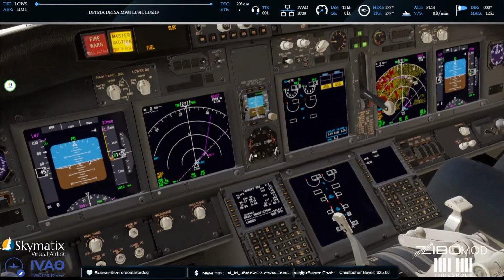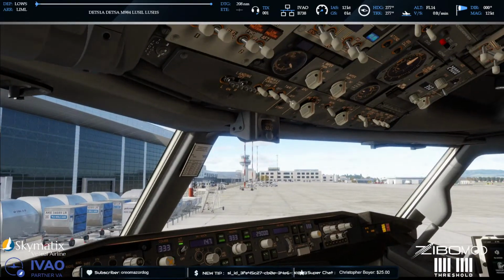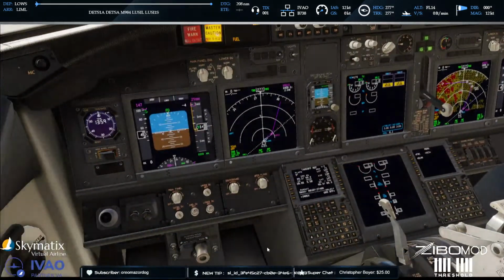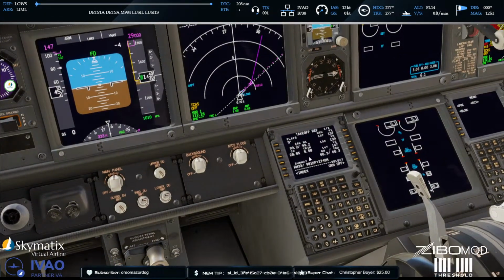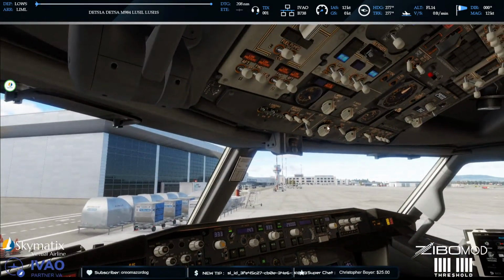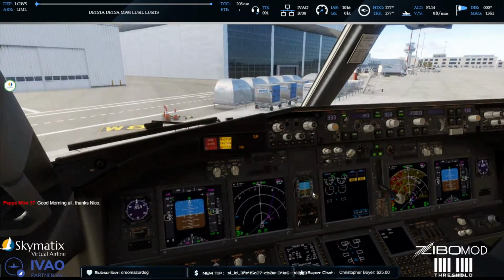Here we go. We are done. Right. 1, 2, 3. There we go. Guys, I make a spectacle of starting the APU because you still get people that are struggling to start the APU. And there's really nothing to it. You click it once, you get it to the middle, you take a breath, you click and hold it for 3 seconds and you let go and you walk away and it just starts. You must just learn to keep it at 3 seconds.